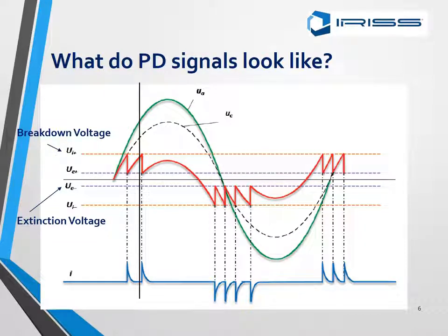So when an insulator is subject to an alternating voltage, charge builds up within the void as the applied voltage increases or decreases. So this causes a series of discharges with charge first moving in one direction and then the other. So this results in PD having a distinctive pattern, as you can see. When viewed in the power cycles, this is what we call a PRPD.